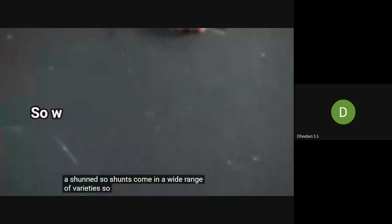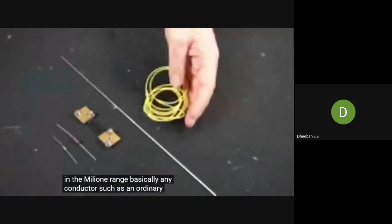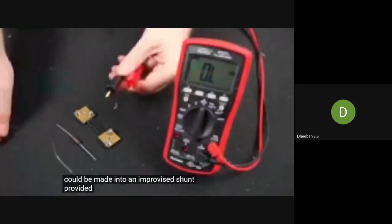So what exactly defines a shunt then? Well, in a nutshell, a shunt is nothing more than a conductor which has some value of resistance, typically in the milliohm range. Basically any conductor such as an ordinary resistor, this wire rod, or a length of copper wire could be made into an improvised shunt provided it has some resistance and we know the value of said resistance.